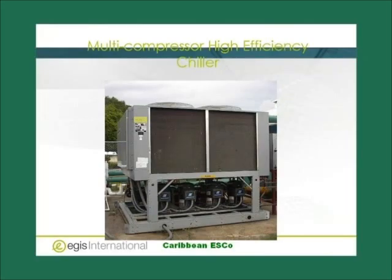Take, for instance, this hotel. It's not a criticism of the hotel, I'm just using it as an example, but this hotel should have a chilled water system where every room is cooled by a chilled water fan coil, and this space cooled by an efficient air distribution chilled water system that will introduce the fresh air, this 20 CFM per person, at half the price, half the electricity cost. That's what we're looking at. That is what we're looking at. By just utilizing the proper engineering approach, the proper unit applied to the space activities.